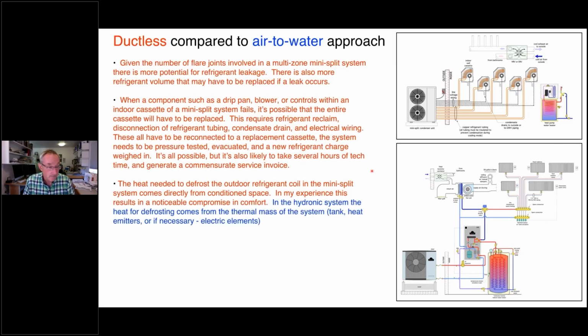Here's another one from that same system. My daughter called me up one night. It was in February. She said, "Dad, how come the heat pump is blowing cool air?" And it was in heating mode. And what was going on? It was in defrost, and it was essentially scarfing heat from inside the building and using that heat to melt the frost on the outdoor unit.